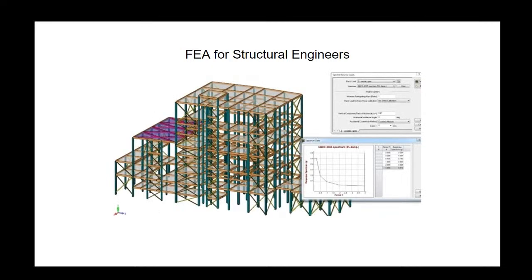But now structural engineers need to simulate loads on an entire assembly of a building at once. So in this case it might be a lot of steel beams and concrete slabs. Using the same process of meshing each part into solid elements would be a very slow process and probably require some kind of supercomputer. So in order to simulate such a complex structure, the types of elements they use need to be simplified. Since a steel I-beam doesn't change shape along its length, it always has the same cross-section. Mathematically, it can actually be simplified into a single element in the solver.